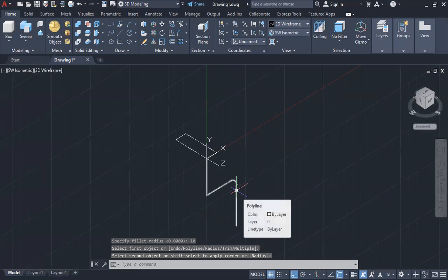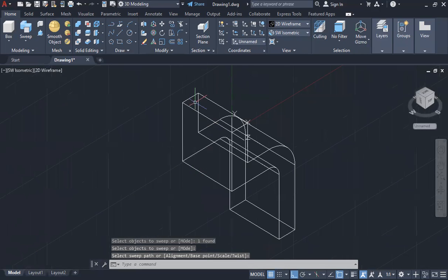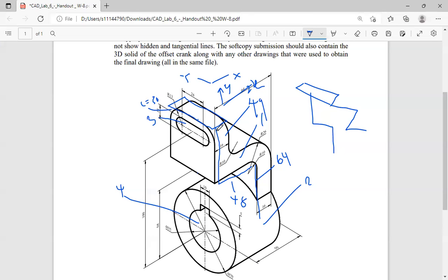How's it, Sam? Alrighty. Okay. Now we're going to fillet our edges. If you look at our diagram, okay, we have filleted edges here. 1, 2. We have a third fillet edge here. 3. And these two have already been filleted because we've set our radius here as 10.